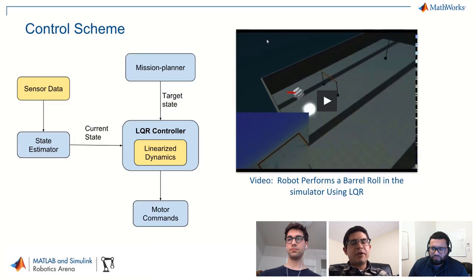We upgraded it quite a bit, and then we based the physics of the controller on that physics model. The key components of those physics are a linear drag and a quadratic drag, and that basically models the water. It's not perfect, but it's computationally tractable.